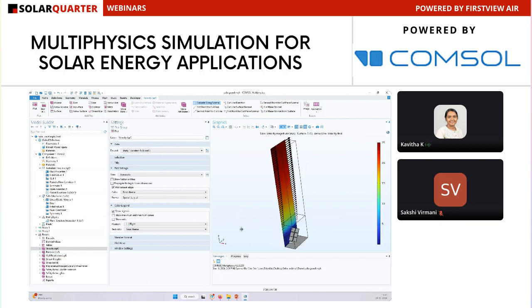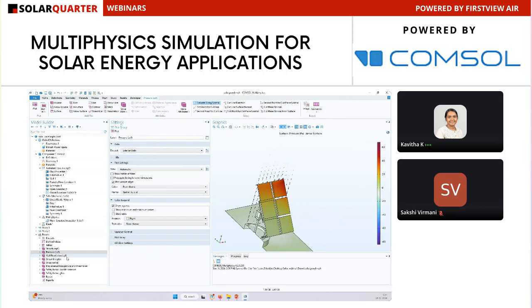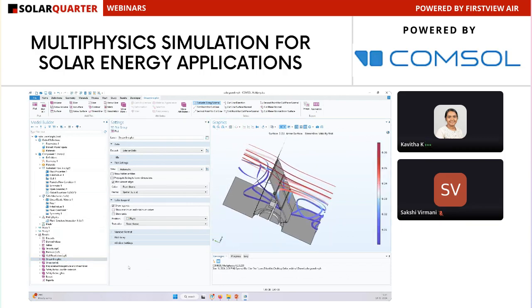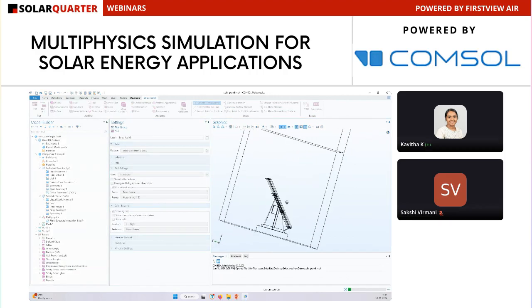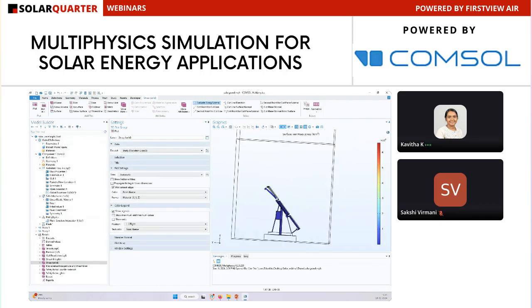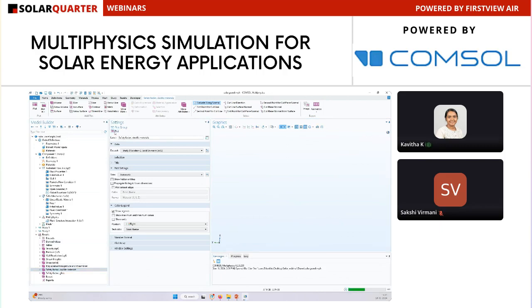So you can visualize the velocity profile. You can visualize the pressure that is exerted on your solar panel. You can have the streamline plot of the wind flow. You can plot your stresses in the form of stress or displacement. Here you can see the stress and displacement due to the wind load. You can also further visualize the safety factor for the ductile materials as well as the glass material.